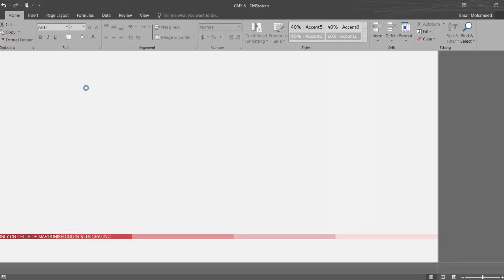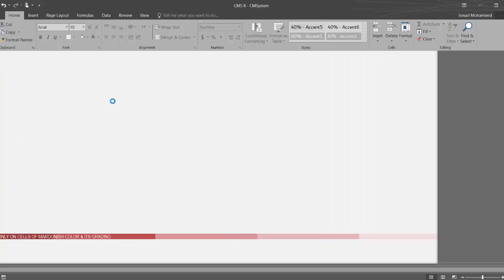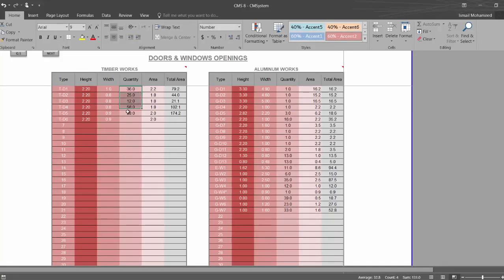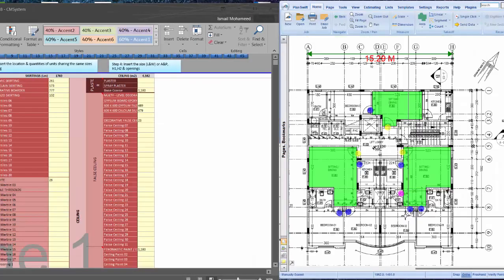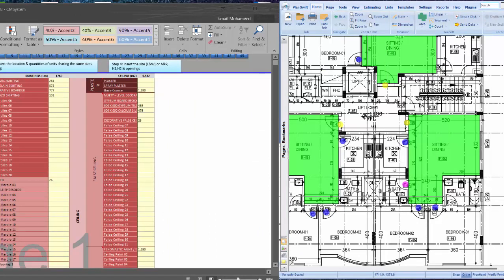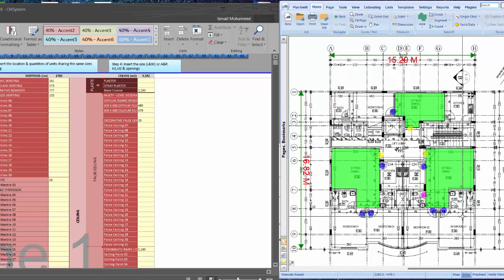But for now we can tell it is by, when we were inserting the masonry work, we have to insert first the opening size. That's the full quantities. Also we took the full quantities with the same method of counting. Okay, and we insert only the height and width from the doors and windows schedule. We will do this for all types of finishing, the same method which we are using in PlanSwift. Okay, in AutoCAD there are separate videos related to AutoCAD.